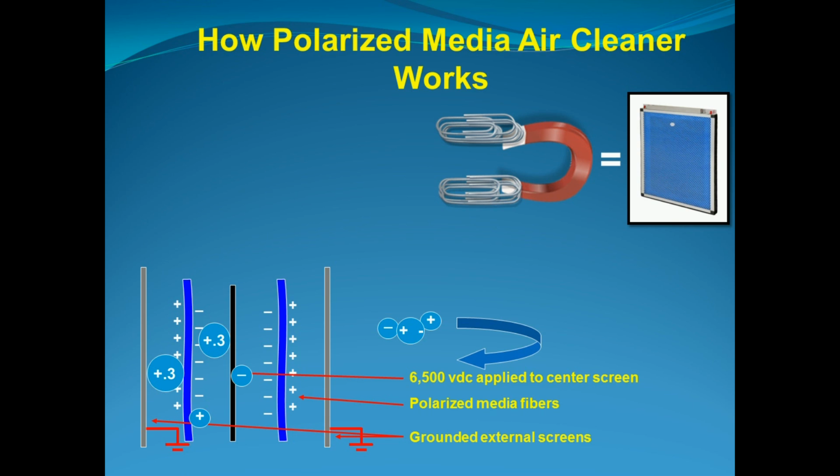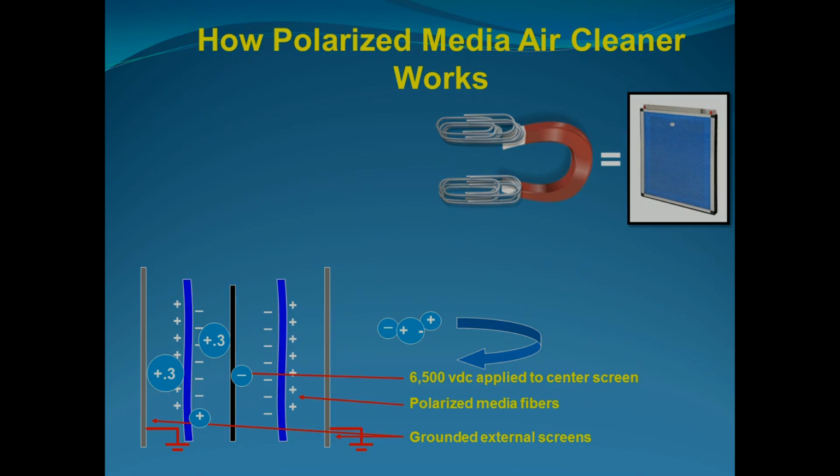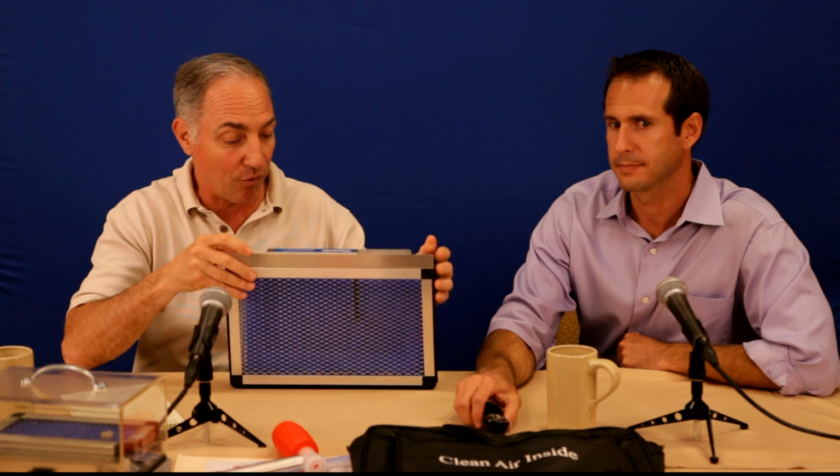And the cool thing also is it doesn't just face load. You get those 1-inch pleats, there's nowhere for the dust to go. We truly have 1 inch of filter media here, and these load from the inside out. So we can hold a lot more dust before it starts affecting its pressure drop. It's kind of like when you've gone from using a 1-inch pleated filter to a 4-inch pleated filter. You just have so much more surface area. And that is a true inch-thick surface area versus just having a thin little sheet of paper that's been creased into a 1-inch frame, but the media of most filters is paper thin.